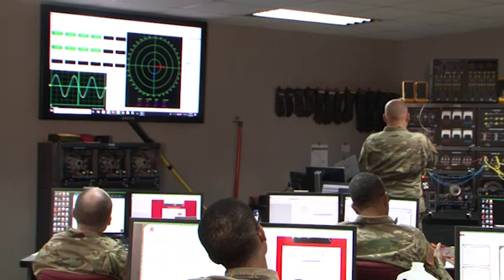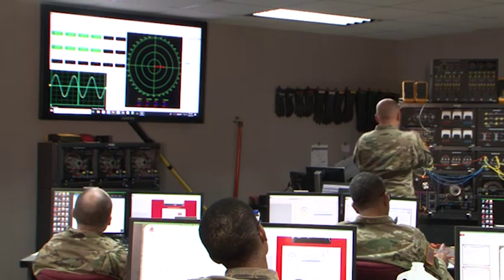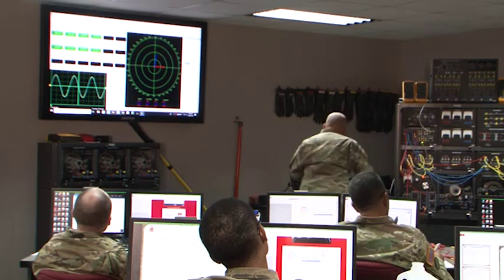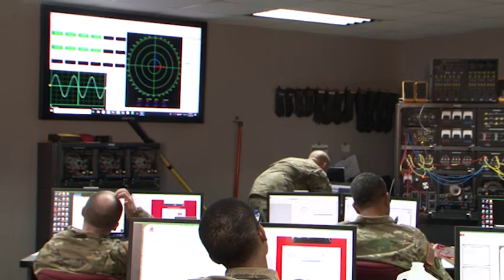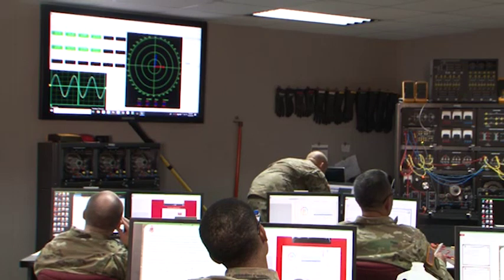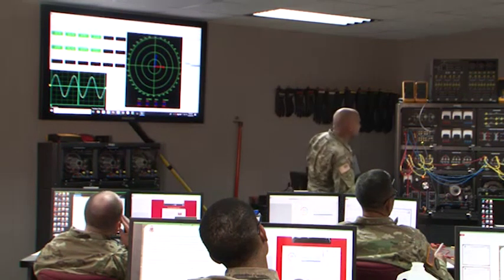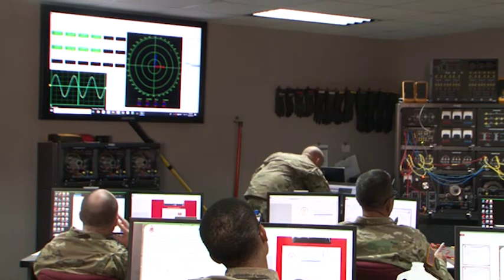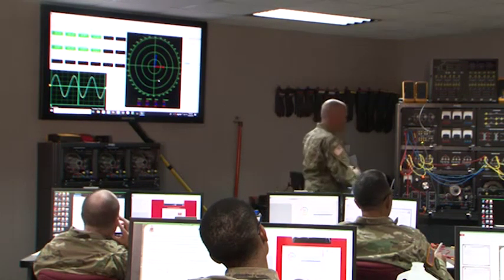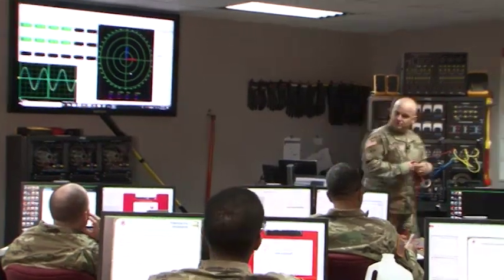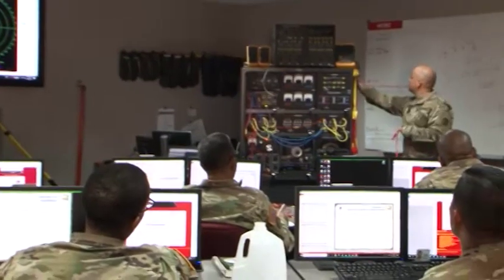Based on that, I can see that I need to. There we go, and that is E2 voltage leading. We have E1, E2, and let me turn that back on. Did I hook up I2? Well, it's in series, so it's going to be the same. Now I'm going to hook up one more channel, channel 3, and bring that back to the source. So we're also seeing source voltage.